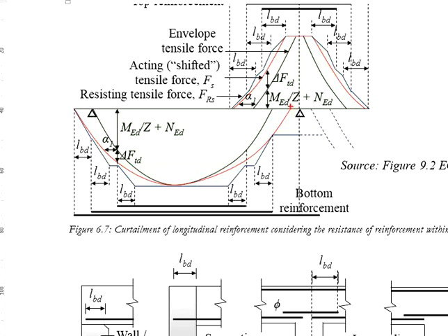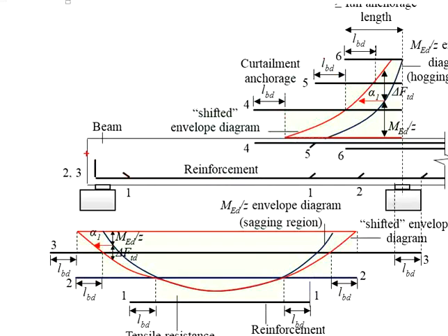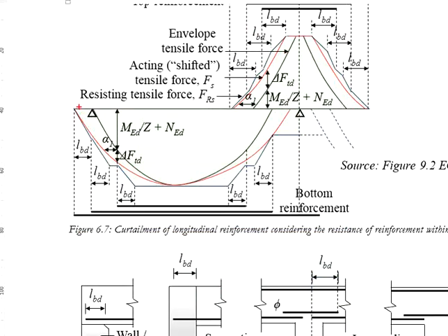And then same principles apply. Theoretically, you can stop your reinforcement here, but normally good practice will require you to go beyond the supports. That's why you extend your reinforcement. And then if you have reinforcement here, go beyond the support here. Make sure it is sufficiently anchored. You might need to bend the reinforcement, something like this. Now, having the resistance provided here being met, then you may proceed with the second group of the reinforcement.